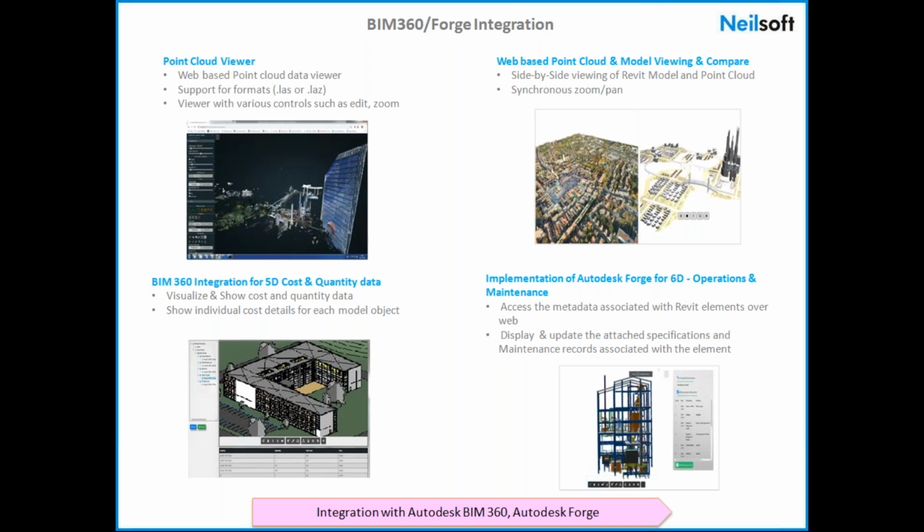The other tool is essentially doing a side-by-side comparison of your model as well as the point cloud data. So when we are doing an as-built model, or when we are converting your point cloud data to a 3D model, while checking, we can make use of such tools where we can do side-by-side comparison, and if there are any issues, then those can be reported back.